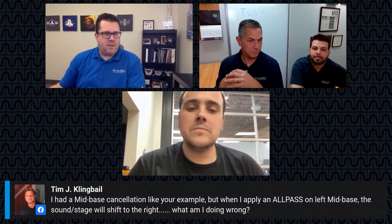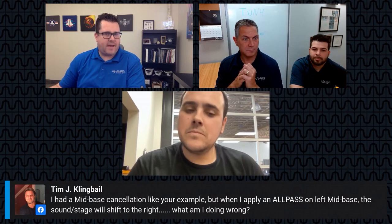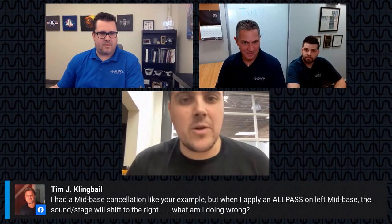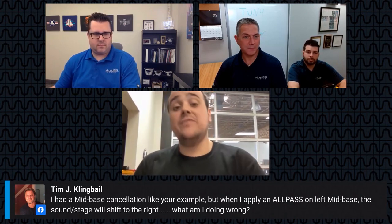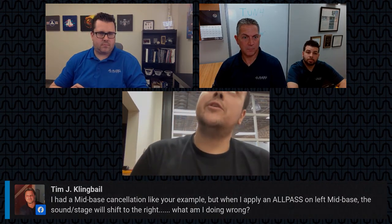Great question that just came in from Tim. I had a mid-bass cancellation like your example, but when I apply an all pass on the left mid-bass, the sound stage will shift to the right. What am I doing wrong? I guess, first of all, we might want a little bit more context. At what frequency range is this effect occurring? How severe is it? And how severe is the magnitude dip that you get when you sum the two? That would be some stuff I would be curious about.